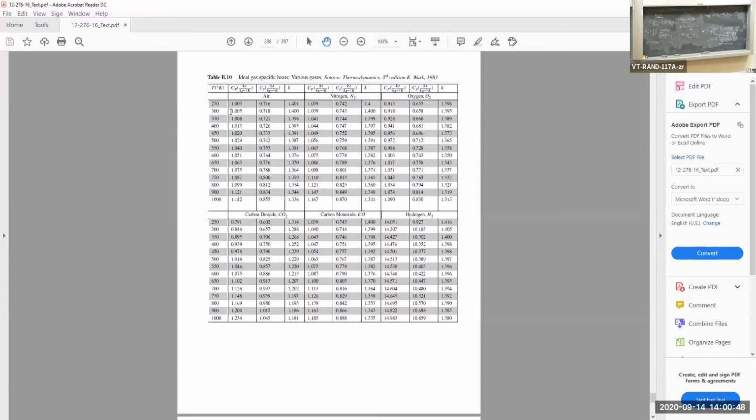So maybe 400 degrees. We start off at about 300 degrees and end up at 500. The average specific heat is going to be around 0.726 instead of 0.718. 400 degrees is the average temperature over the process, 500 plus approximately 300, so that's 400 degrees.